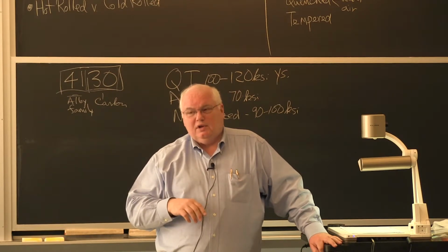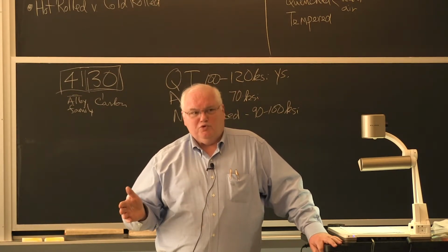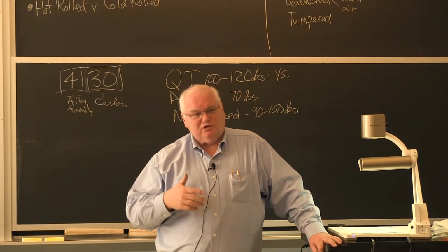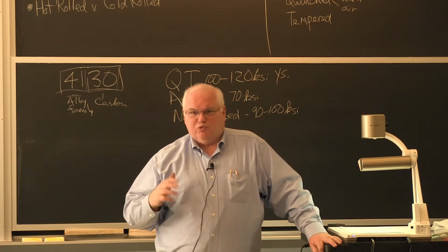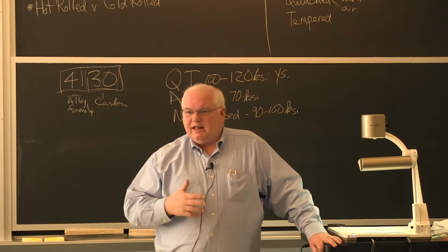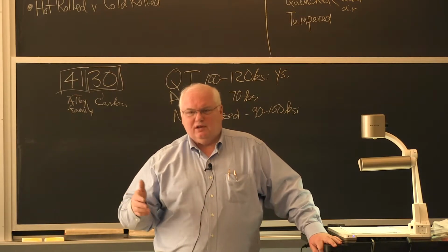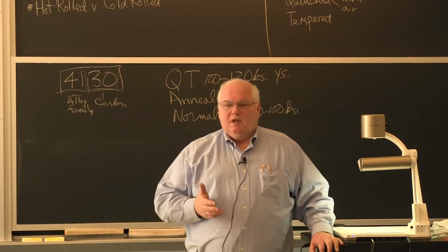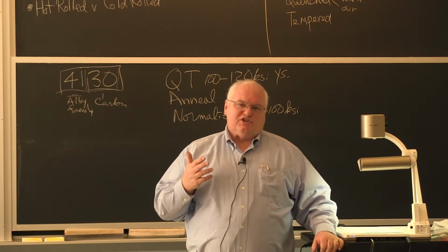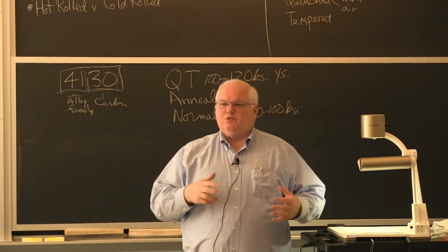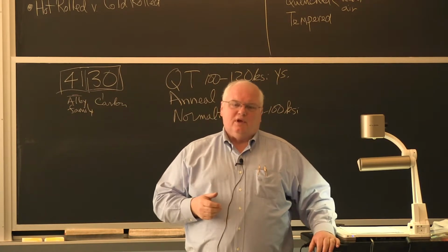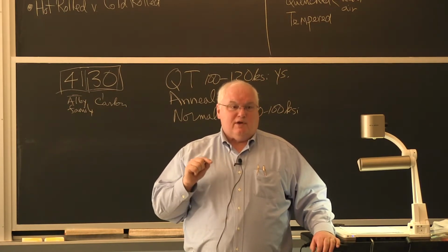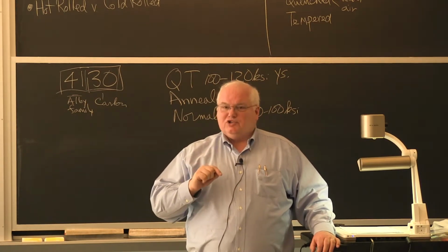And what had happened? Someone electroplated it. When you electroplate the steel, you introduce hydrogen. The steel's embrittled. If that thing gets shipped to him, and whoever did it didn't bake out the hydrogen, and the steel's embrittled and it starts getting stressed within a few days or a few weeks, you have a brittle material, and it can start a crack.